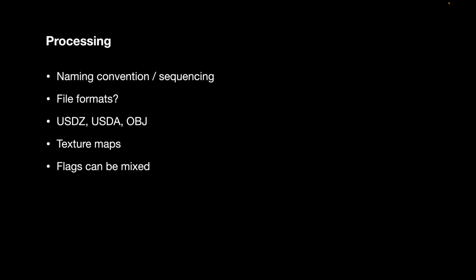So you would probably have to convert that to other formats. EXR, which is the standard file format that we use in visual effects, I haven't tried, so I don't really know. But in my experience, I wouldn't recommend using 16-bit or HDR photographs for generating point clouds, because the files are bigger, the depth information is also bigger, and it will take more time to calculate a point cloud. Low dynamic range images like JPEGs or PNGs work perfectly fine.